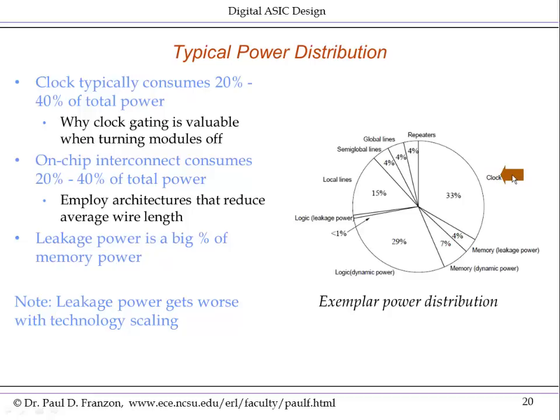Frankly, there's a good argument for absolutely minimizing the number of registers needed in a design to those simply needed for the logic function of preserving data between clock cycles. And this is one of the reasons, because of clock distribution.